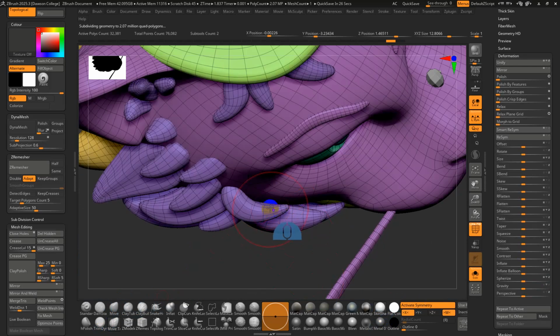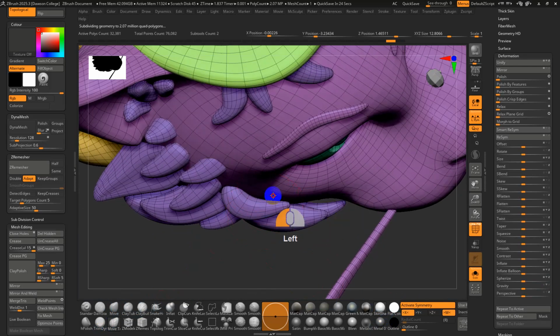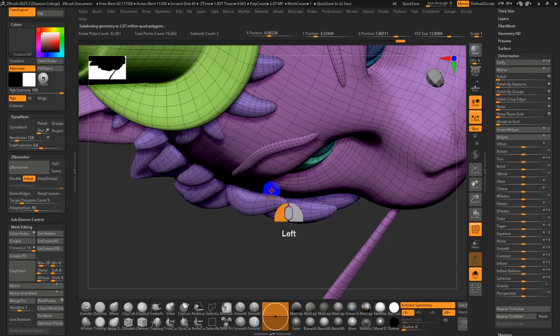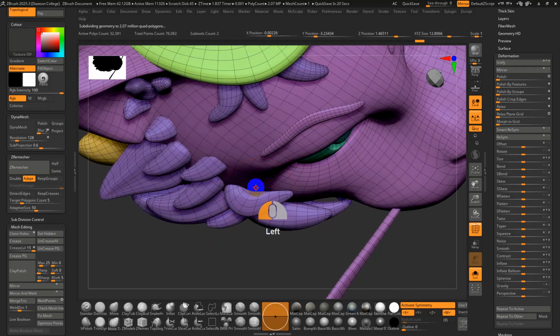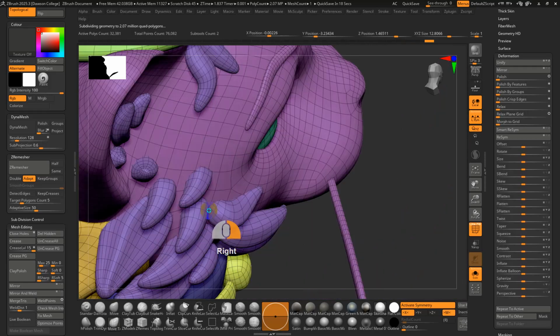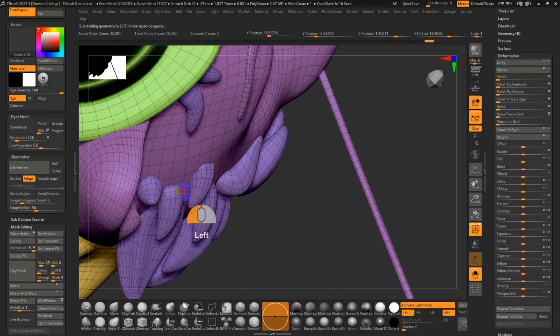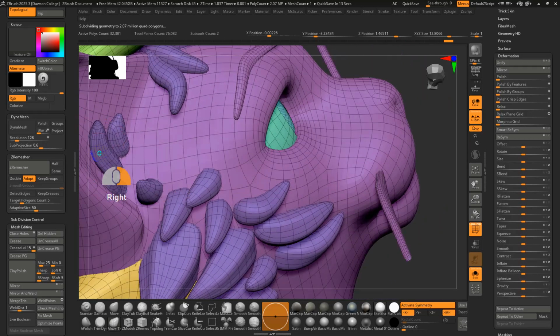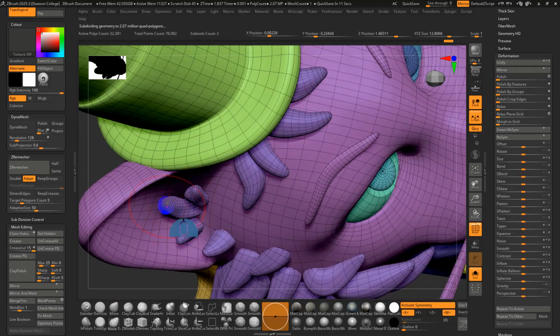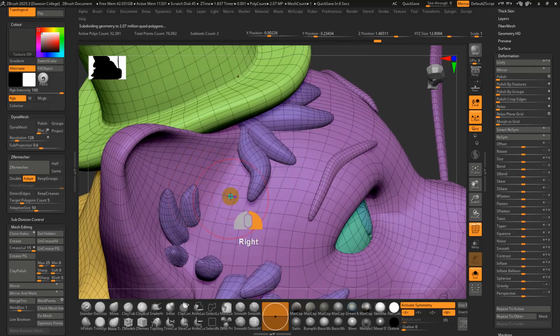Here, I'll go to skin shade 4 so it's easier to see. Then I can grab this and put it flush against the face, so we don't have this pulling off and creating these micro cavities that can be difficult to print and create a ton of mess. Because then you get messy supports, messy cleanup. So again, we want to try to avoid any tiny gaps and overhangs.